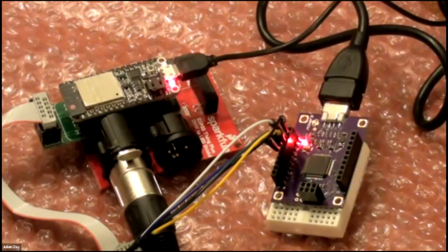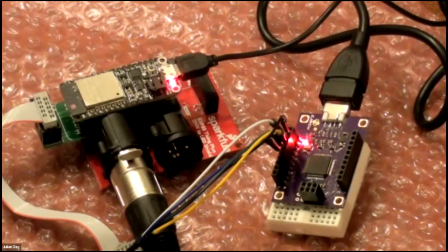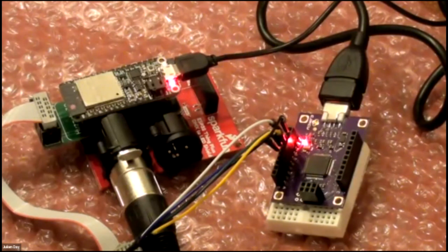About the only instruction which is standardized is the bypass instruction, which is used for effectively telling the device to ignore commands. It basically puts a 1-bit data register in the data scan chain. But most of that's hidden for you by OpenOCD. If OpenOCD supports a particular device, then mostly you don't have to worry about what JTAG itself is actually doing. Right, okay.